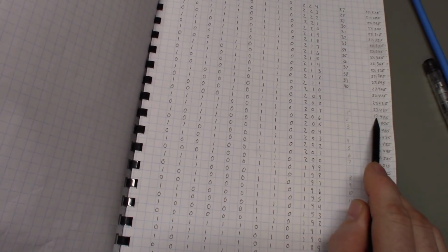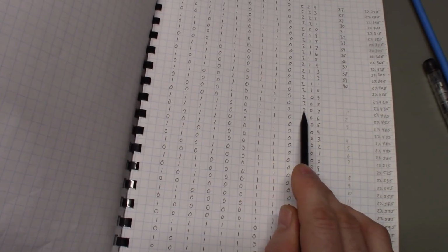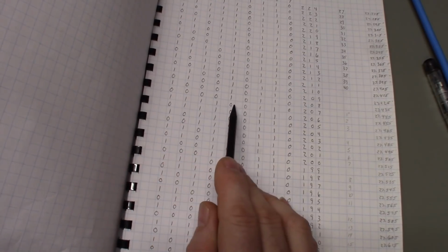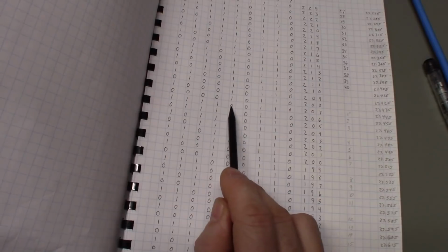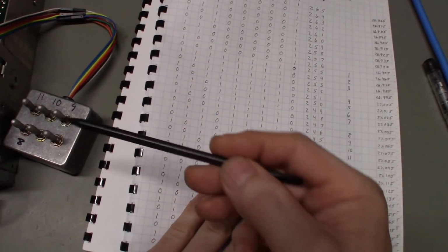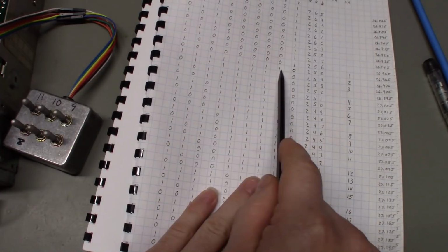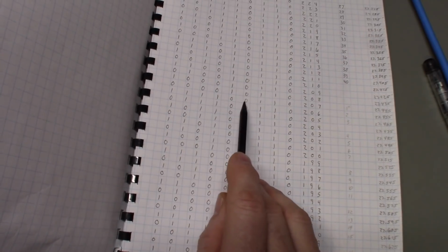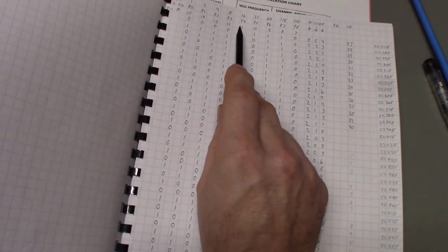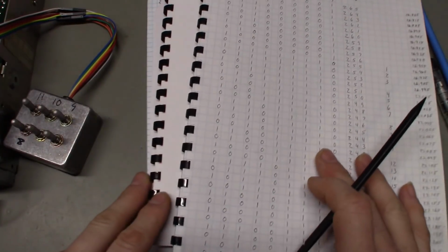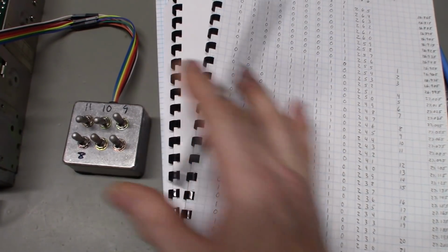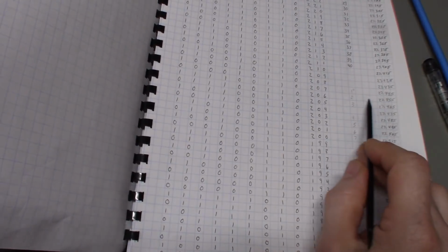But it's very easy if we skip 3 frequencies after channel 40. Look what happens at 27.445, which is decimal number 207. We get lots of ones, which is what we're looking for: 1, 1, 1, 1, 0, 0, 1, 1, 0. So the only difference between what's coming out of that channel selector switch at channel 1, which is all ones and a 0, and decimal number 207 is that only 2 pins are different, pin 11 and pin 10. So if we take pin 11 and pin 10 and flip the switches down, this radio is now on 27.445. It's just that simple.